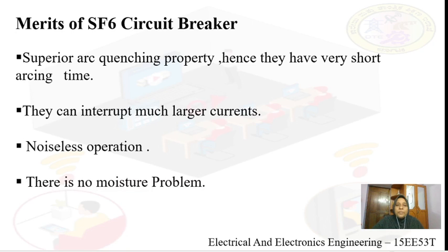There is no moisture problem. When we were understanding construction, we understood that SF6 circuit breakers have got sealed units. So once they are sealed, outside moisture cannot enter inside the SF6 circuit breaker. So the moisture problem is not present. No risk of fire. When I was discussing the properties of SF6, I told you it is non-inflammable. That means it cannot catch fire. That is why you don't have risk of fire.